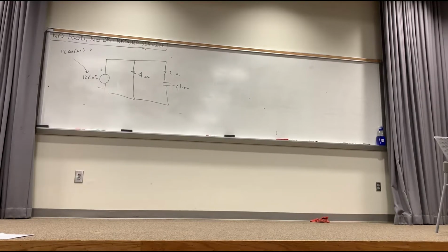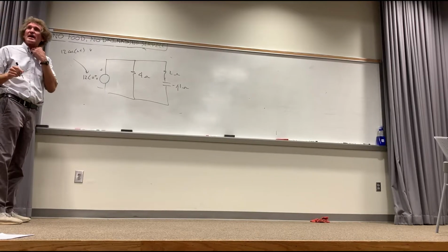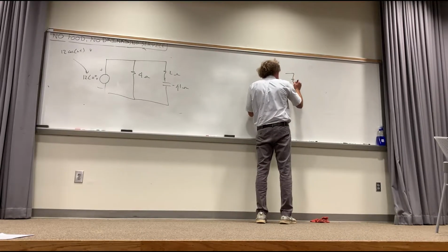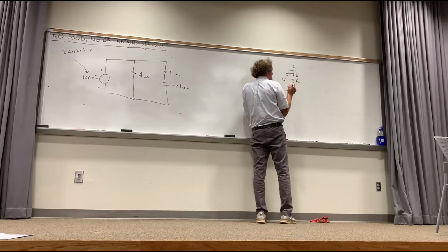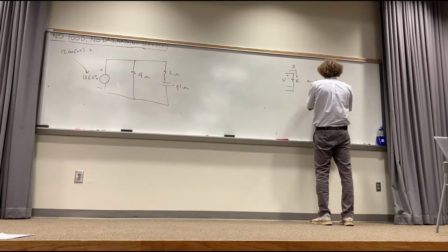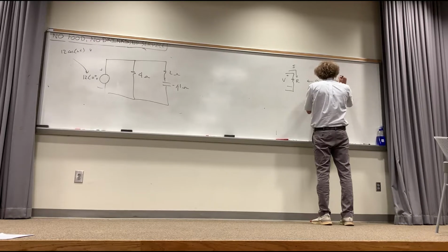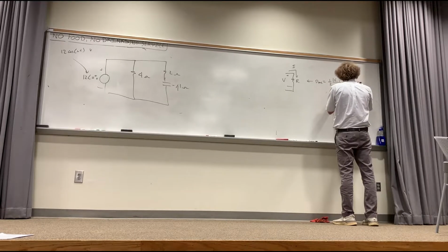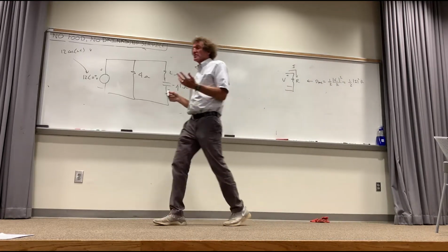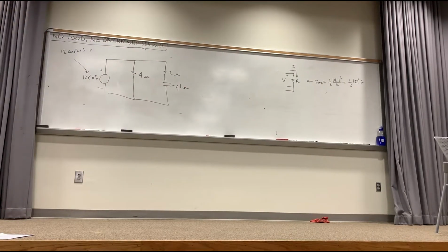Our goal is to get the current, and the reason we want current is because once we have current, if we have a resistor like such, and we know the current I or the voltage V, and those are magnitudes, then I can say that the average power, P_av, would be equal to either 1/2 times the magnitude of Vm squared, over R, or it's equal to 1/2 times the magnitude of I squared times R. And the reason you like these equations is because they're very convenient and quick to use for average power. Now it's using the magnitude of the voltage or magnitude of the current.